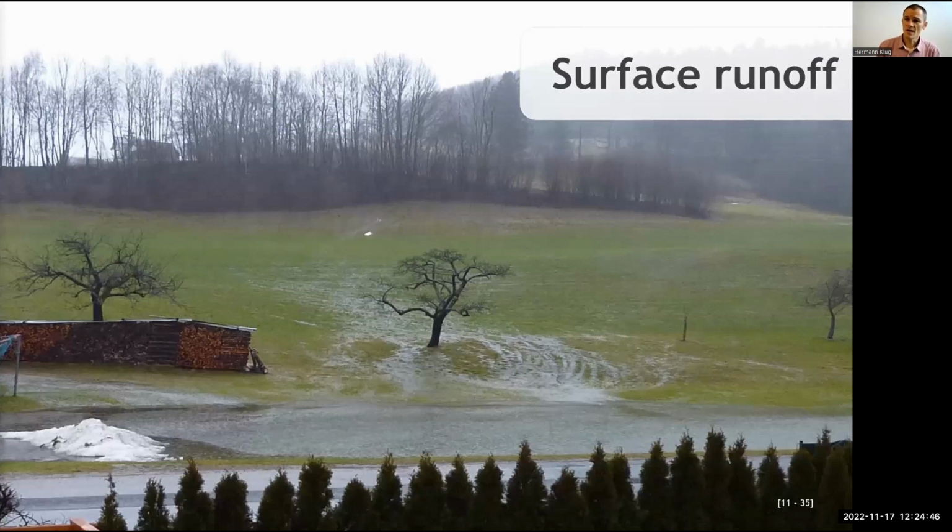This is how it looks after a few minutes of rainfall. We have local retention basins by purpose. You can see here the part of the soccer goal; that is a meadow which is used for playing soccer, you will see that in a later picture. But at the same time, it's an area functioning as a retention basin so that the streets and the infrastructure are not compromised.